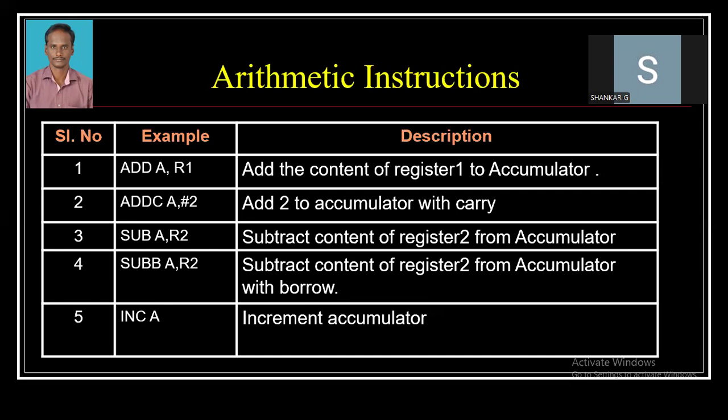Next, SUB A, R2. It subtracts the content of register R2 from the accumulator and the result is stored in the accumulator. SUBB A, R2: subtract the content of register R2 from the accumulator with borrow and the result is stored in the accumulator.